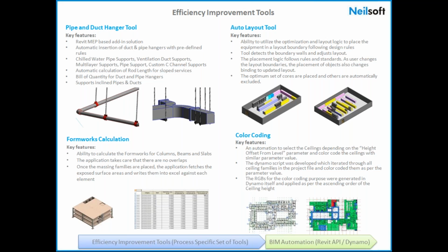And another example developed in Dynamo is for MEP. While doing the layout of pipes and ducts, it is very important for them to visualize or understand how the ceiling height is varying across the floor plan, so that they can place these pipes and hangers in an optimum way. So that is where we develop small scripts which help in improving the efficiency or improving your workflow, which is what we can see here. We have developed such tools for different customers. Some of these tools we even make use of within our own BIM modeling process.